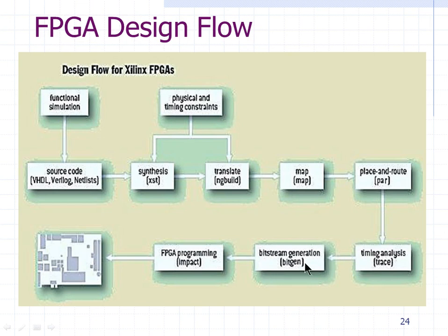Then you do something called bit file generation. A bit file is a file that is used to program the FPGA. Then you program the FPGA, which is on the board. So this board and the FPGA on it will start acting like this design that you have created in Verilog. All of this has to be done for FPGAs or ASICs.